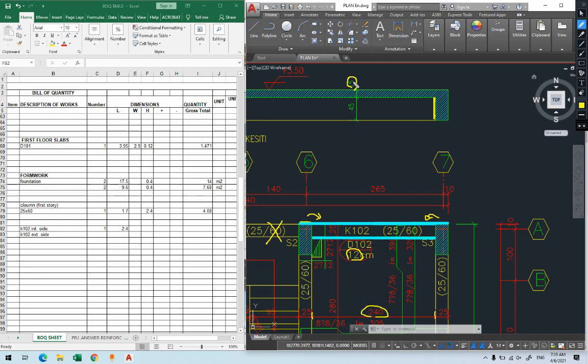Look, you're not supposed to look at this one here. Look at the slab which we have here. But the idea is, you take the slab thickness. This will be the remaining for the inside or interior formwork. Now the slab here is 12. Remember, the slab here is 12 and the beam is 60. So 60 minus 12 will be 48 for the inside part.